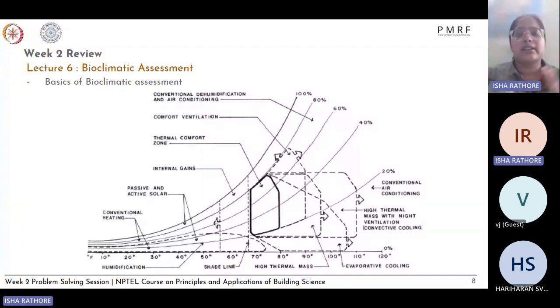So if your outside peak is at 12 p.m., then the inside maximum temperature is achieved at 2 p.m. So this time lag of 2 hours is how the thermal mass moderates the outside temperature to inside temperature. And it also causes a temperature reduction. So if the maximum outside temperature was, let's say, 40 degrees centigrade at 12 p.m., then the inside temperature at 2 p.m., which is the maximum temperature, would be close to 36 degrees.